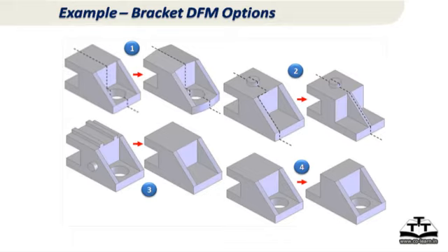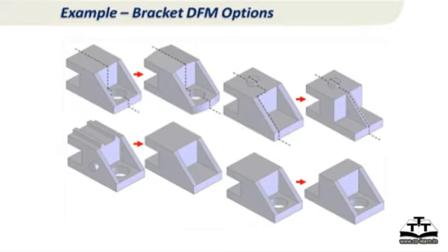The fourth one, an overhang portion is removed. It could make your casting simplified or even machining simplified if you are to machine the pocket. Okay. Now let's take a look at a little more complicated problem.